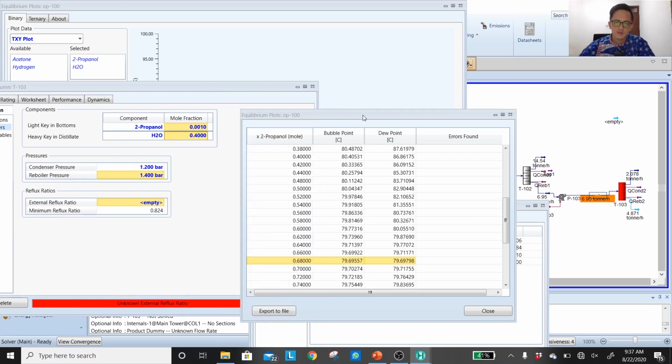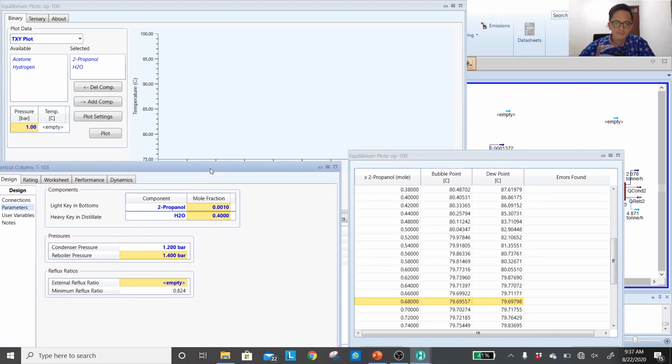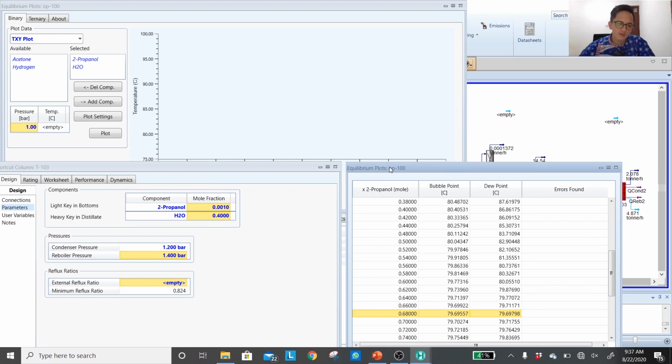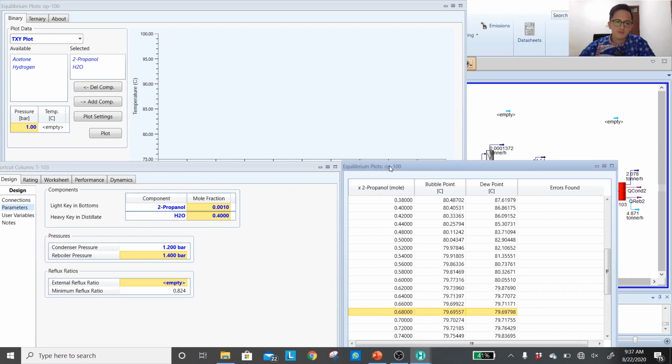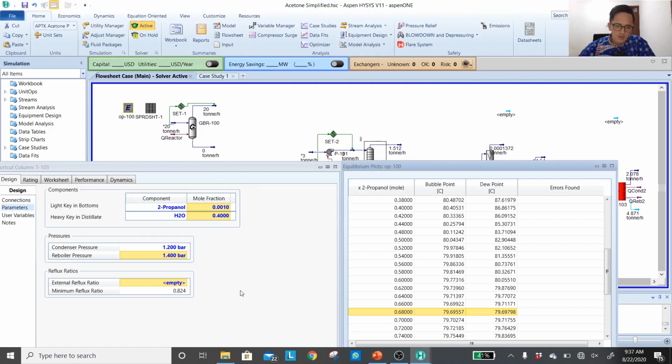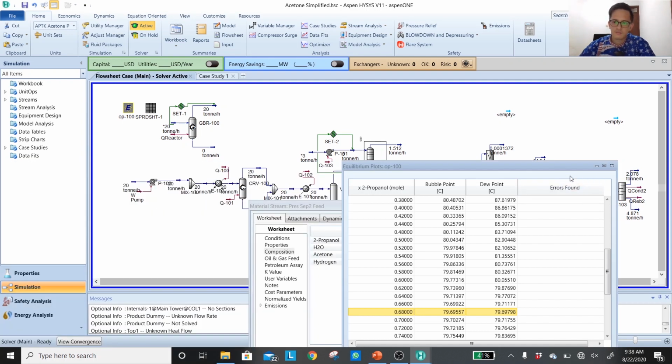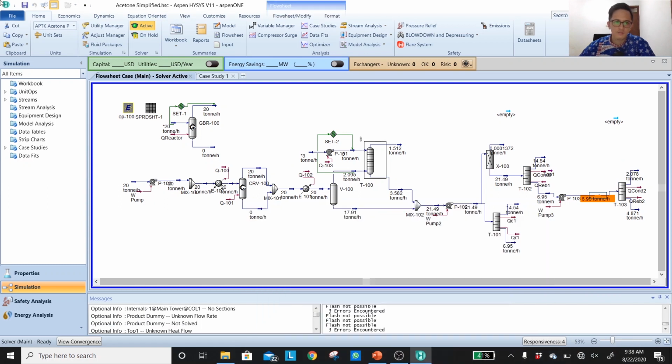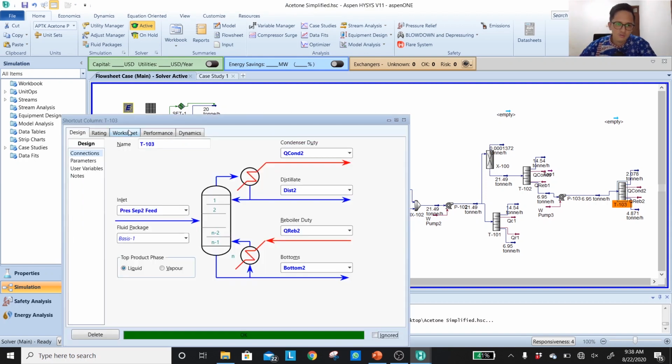Okay, done. So that can be solved, but again, back to our fundamentals. Use your judgment, use your engineering sense. Now we're working in the left window of the azeotropic condition, so now it can be done. Okay, 0.824, give another 20% allowance. Let's say it's 1.1. I'll save it. Okay, so check the composition now.